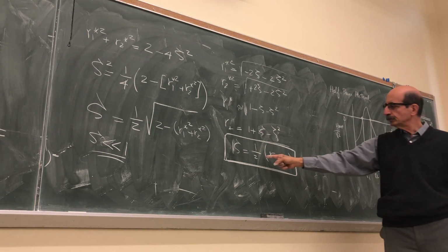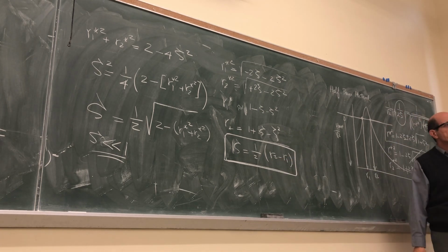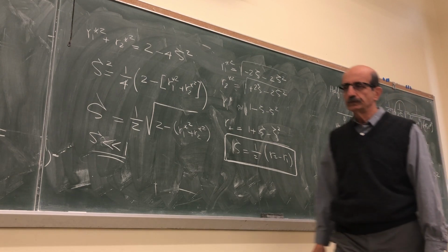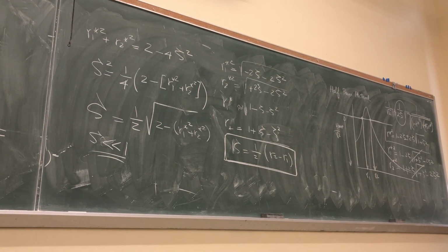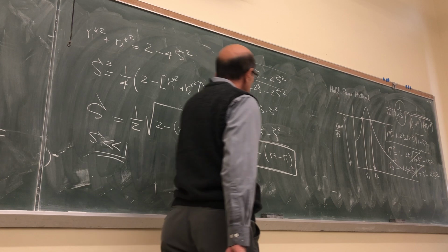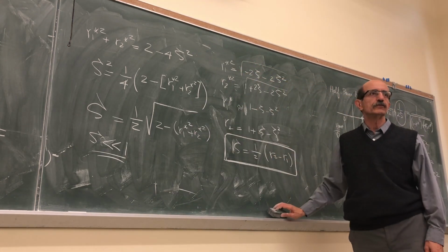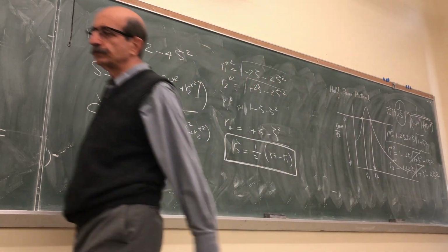The damping ratio would be related to the difference between these two frequencies. So that's another way to evaluate the damping ratio in a system, which is based on the power of the system. We don't get into that, and it's called the half-power method, but that's really the practical way to find the damping ratio in the system, in addition to using that Q approach.